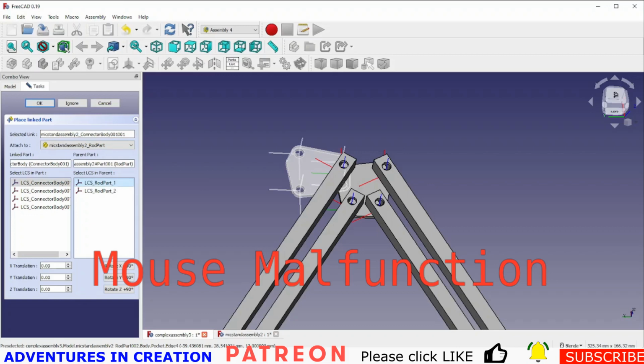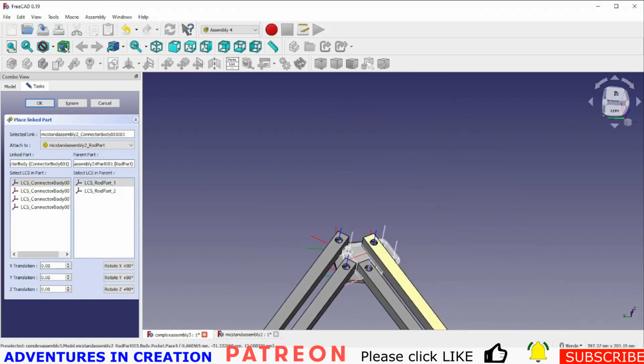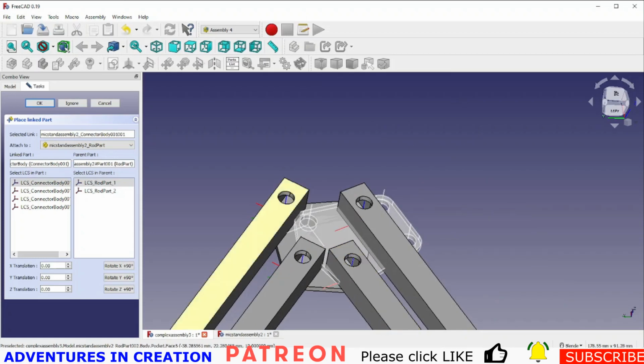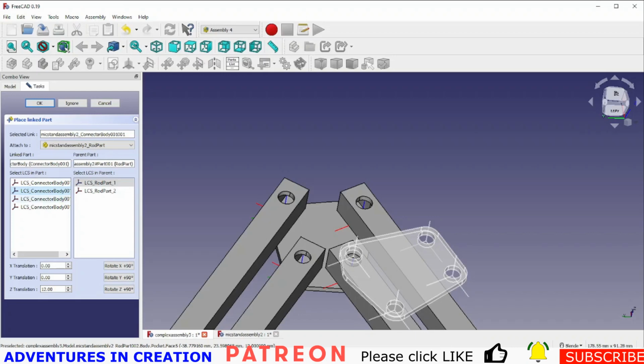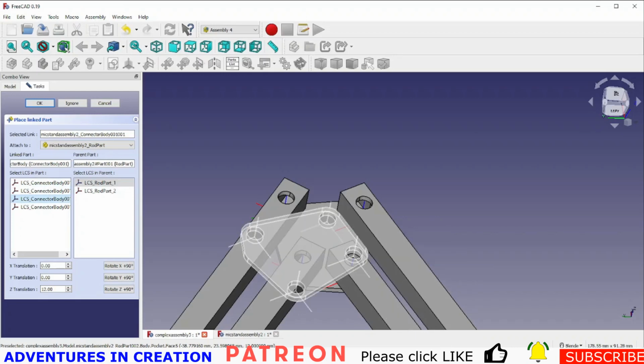And by LCS1, and I can already see that I'm going to need to offset it in the Z by 12, I think, is my thickness from memory. Yeah. And then I'm going to connect it by different holes until I get the right one.